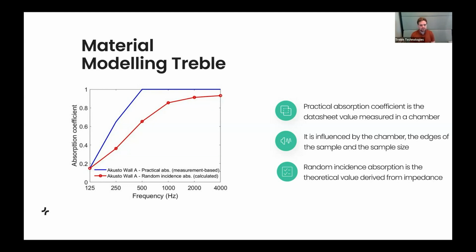And for the time being, this is a porous material builder only, modeling the normal incidence of sound. That means, as I will demonstrate in a little bit, that you can, for example, define the absorber as having a certain air gap, certain thickness, certain density. Based on that, we calculate the impedance.